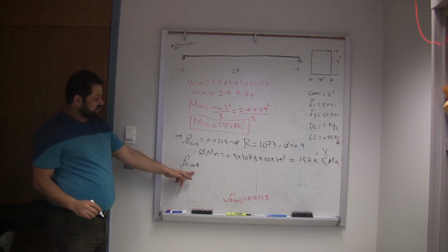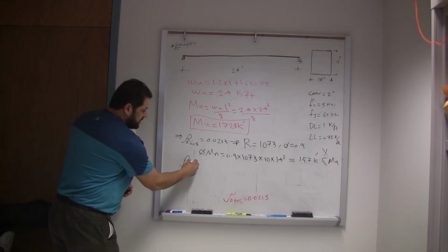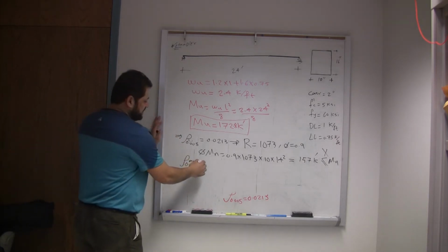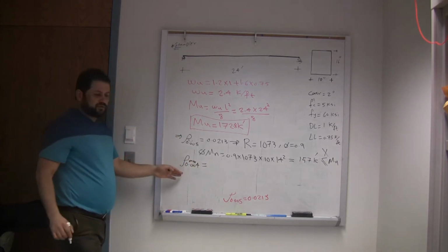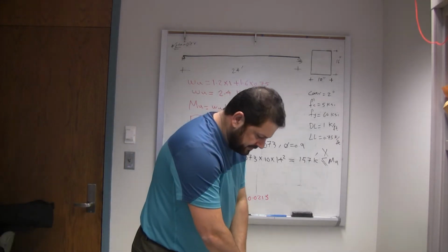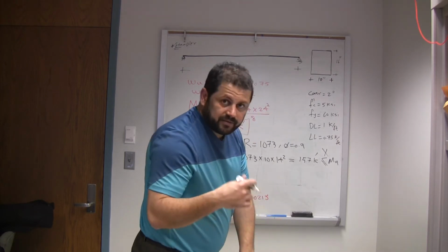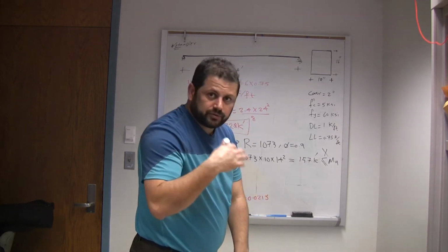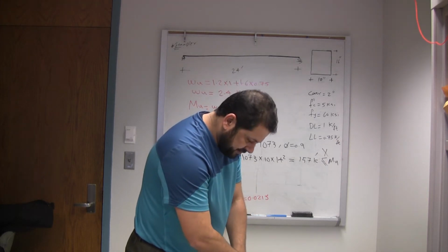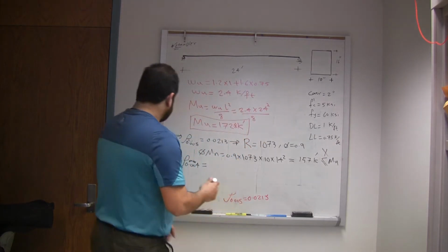Now let someone try to go with rho max. When the strain in the steel is at rho max, the strain in the steel will be 0.004. That's the maximum the ACI code allows you to do. And rho max can be calculated by an equation. We went over all of these calculations and explained it really well. But rho max for that is 0.0243.